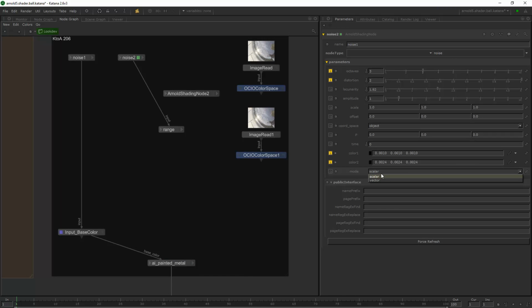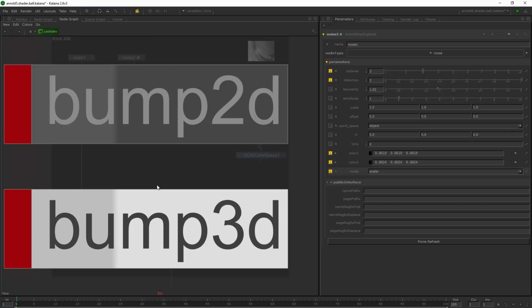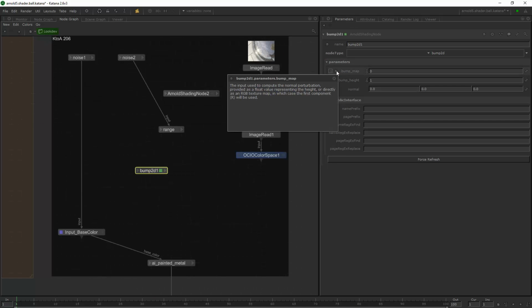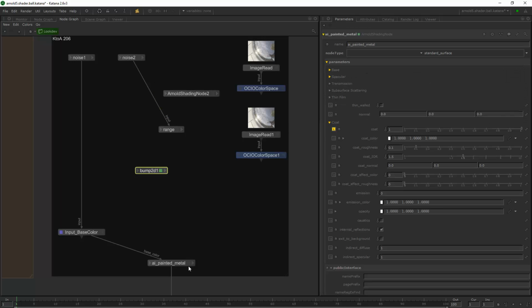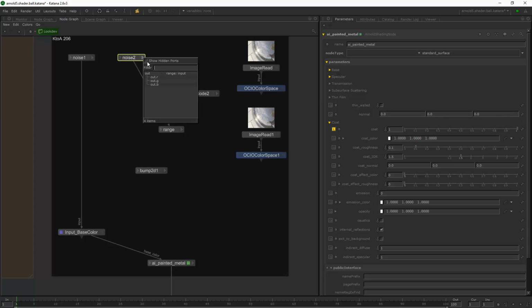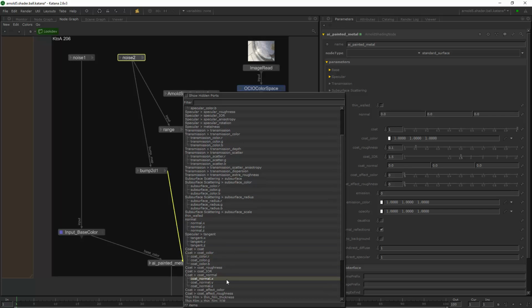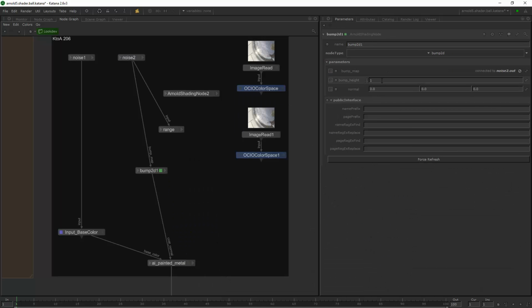So I think if I use a vector instead, or just a scalar and create a bump, bump 2D, which should get the map, float, height, RGB. So when I connect the RGB texture, in which case the first component R will be used. Okay, so bump height normal. So I could actually try this now and connect this to the map and out to the normal, code normal. So now we've got a height. Let's see if that works.